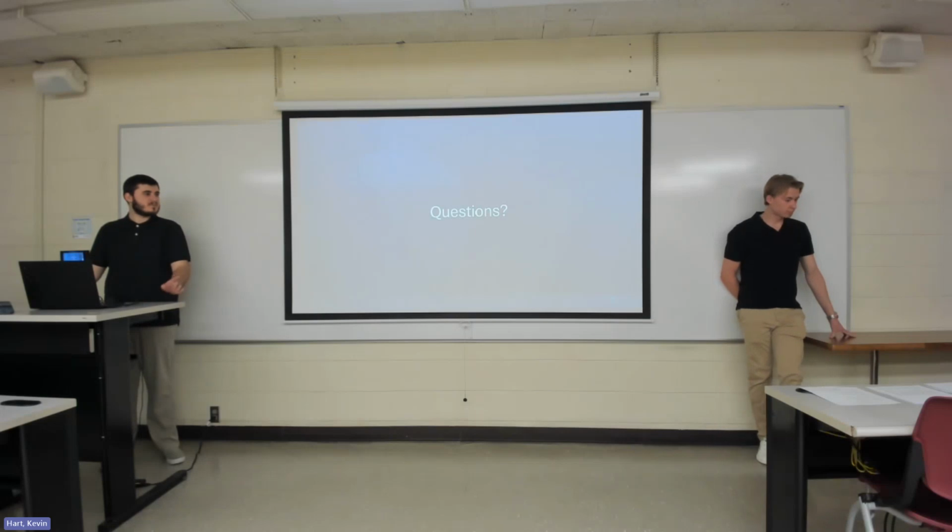And last question was about DMLS. Do you know how much time it will take to print? They said about 2-4 days turnaround time, so it's fairly quick. Yeah. And the post-processing is time consuming for DMLS. Depending on the shape and contours of your part, the organization is going to do the post-processing as well for you? Yes, correct. That's great.